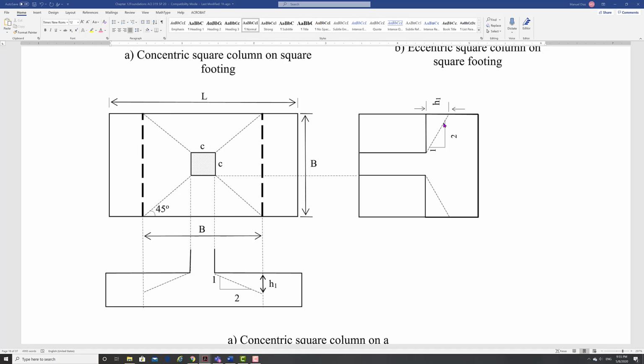That's what I said, whatever you hit first controls your area. Okay? And so notice again, the area of the foundation using that formula is not the area of the footing, it is this area right here, which is different. Okay? So be careful then with that area too, because it's not the same as the area of the footing.